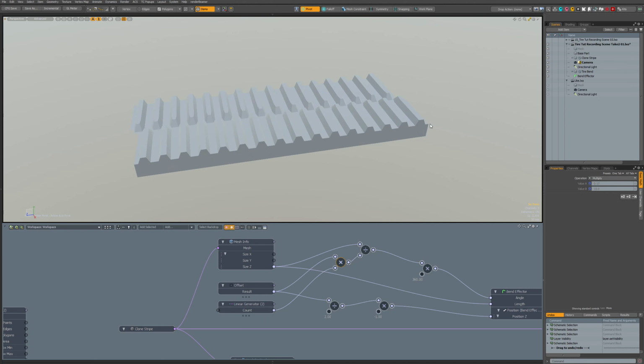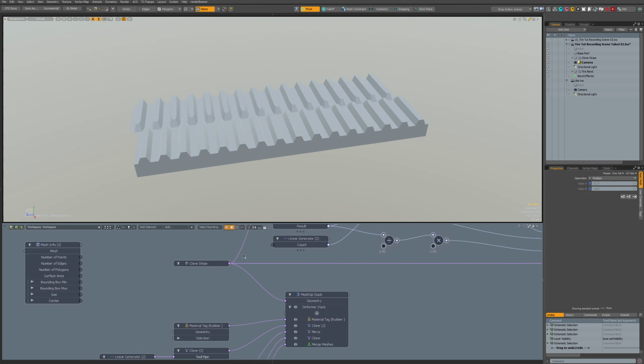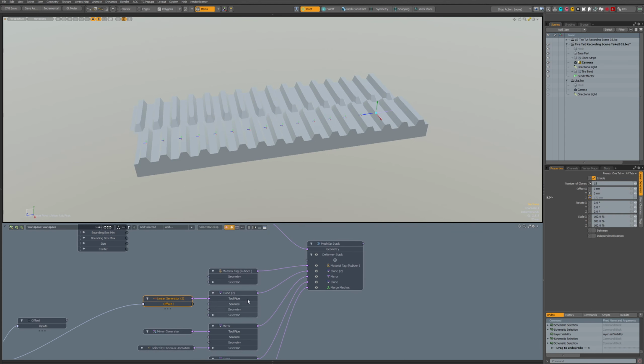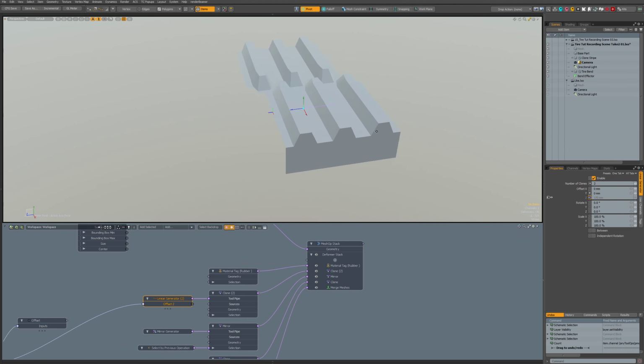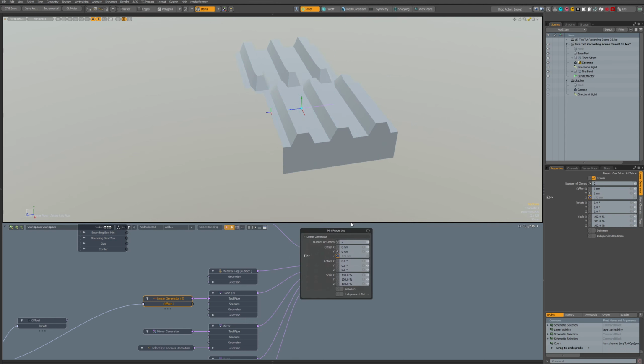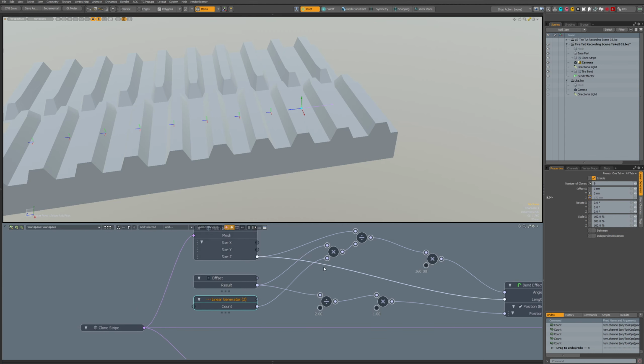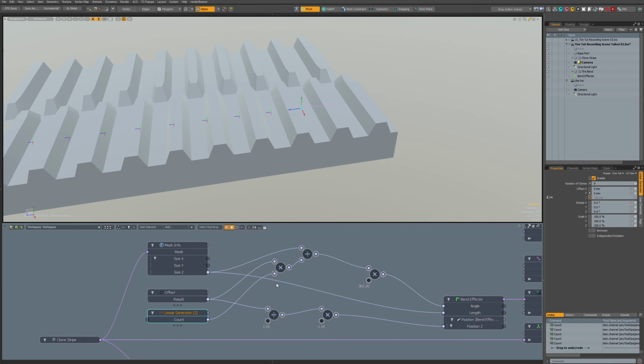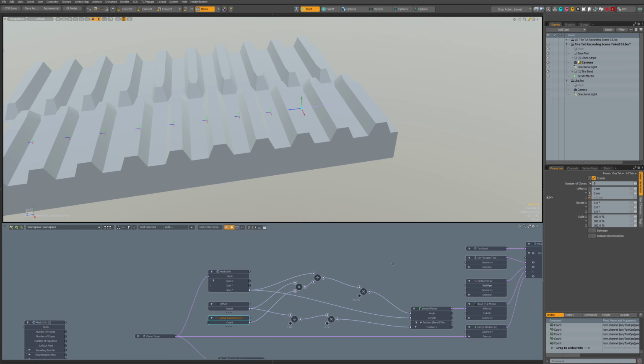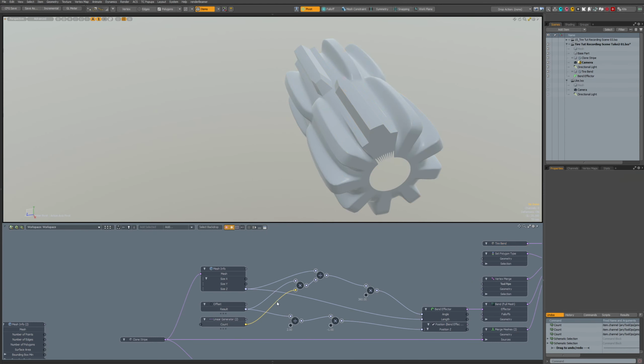So we get this length, but as we use this clone operator straight, if we make it like 2 here, the number of clones is 2, but we have 3 parts there. So there's always one part more than the number of clones, because it's the number of clones, not the total parts. So what we have to do is add 1 here to the count.